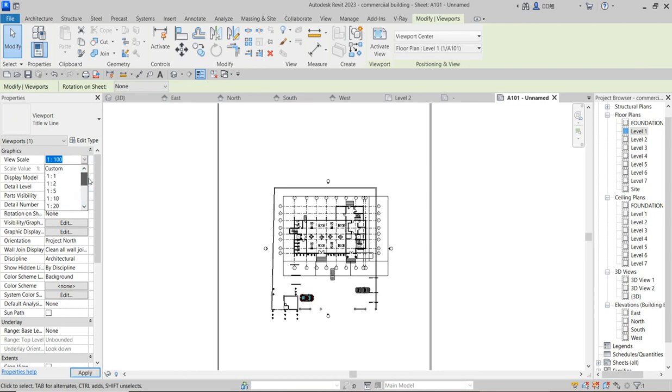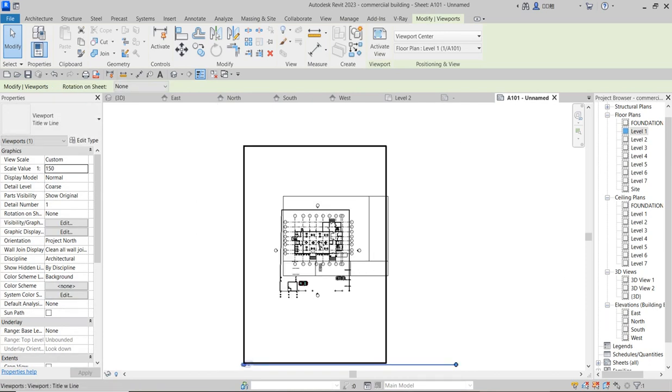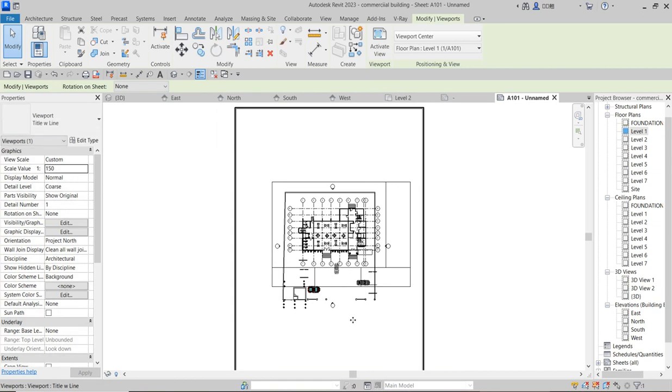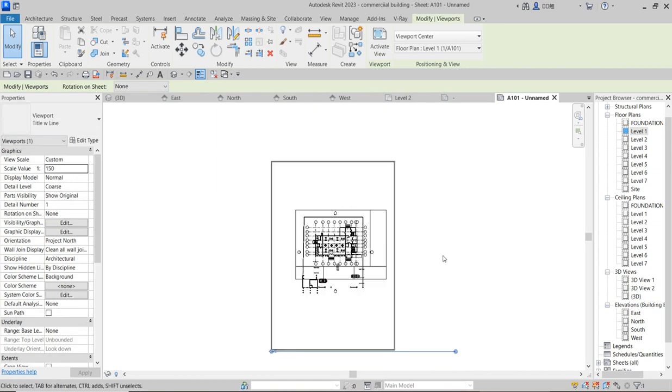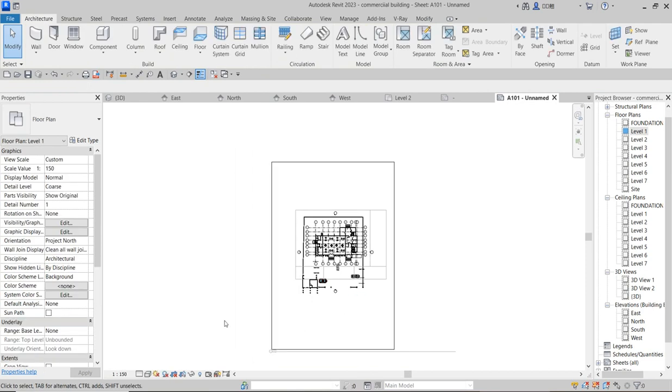In this scale, there are two options. You can customize your own. I'm going to use 150, scale 150, to see whether it will be helpful. Yes, I think this one stands directly. So now from here you click inside, double click, so that you'll be able to access the whole drawing from the sheet. Then you'll be able to crop the area that you intentionally do not need.